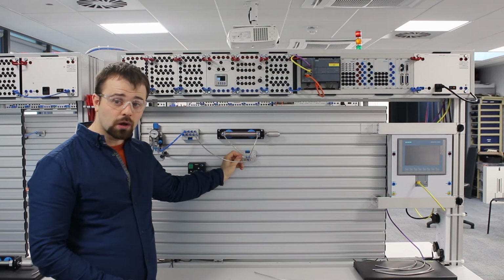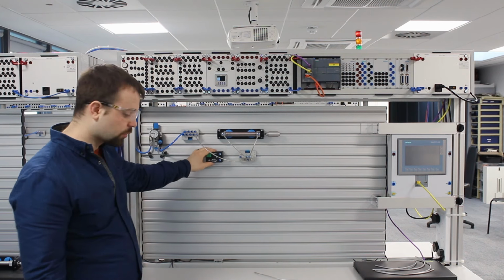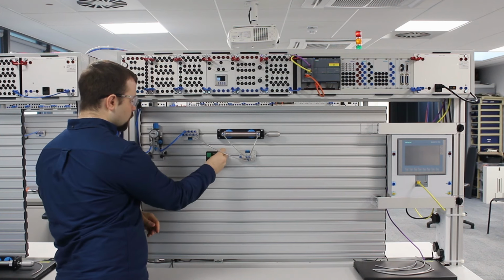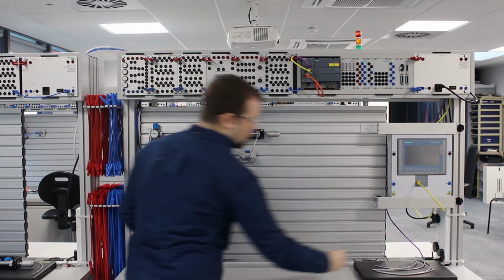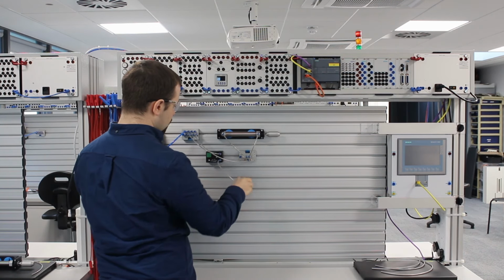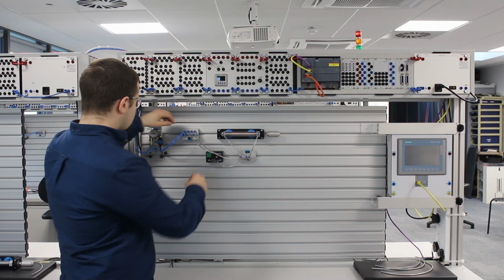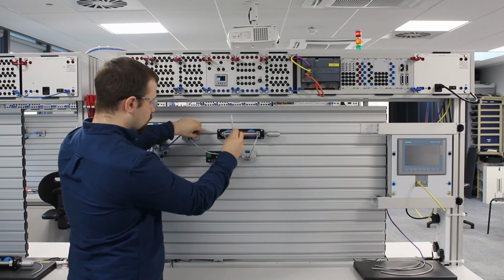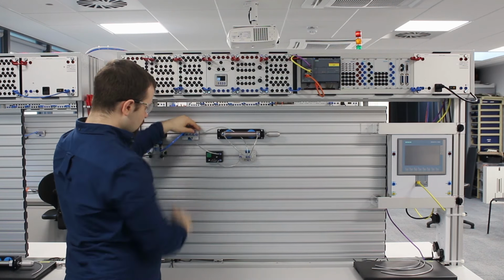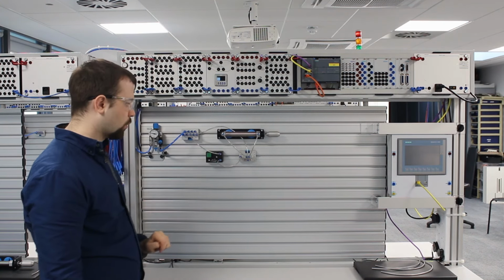In order to make 1-4 activate, we're going to be using the same 3 two-way valves that we were using before. So, air from our manifold into port 1, and then from port 2 into 1-4. Now, it might be getting a little bit confusing here, so again, I'm just going to tidy up and pass wire 1 up through the back of this cylinder and out of the way, so that I can more easily get to my push button here without stuff in the way.